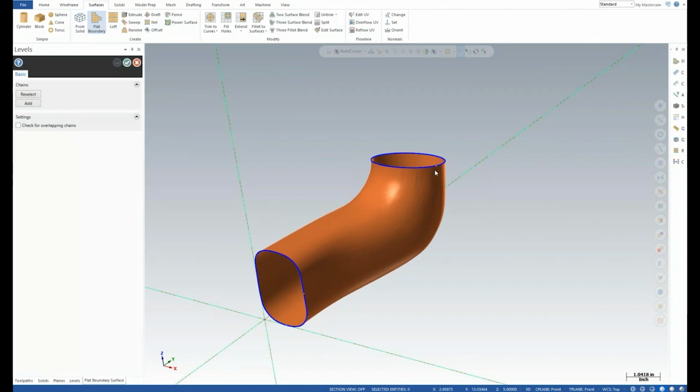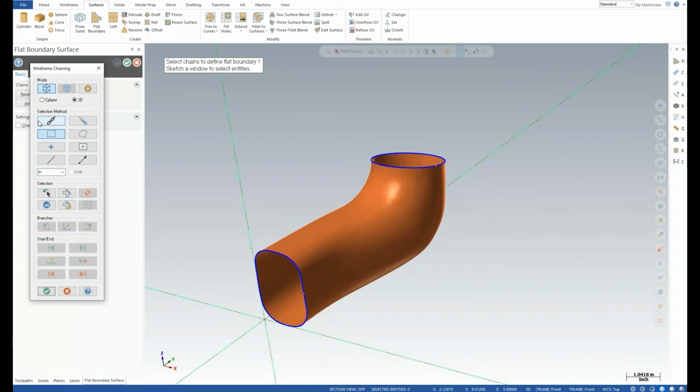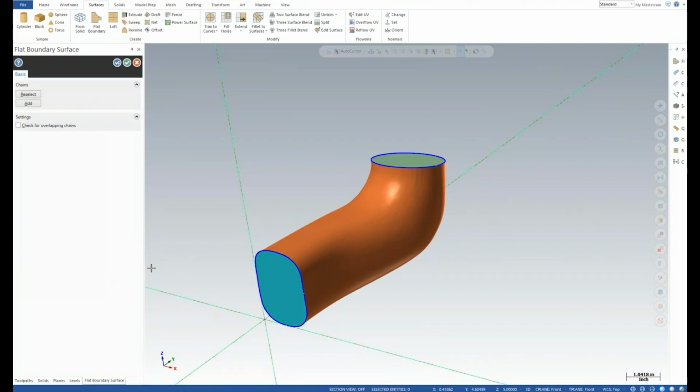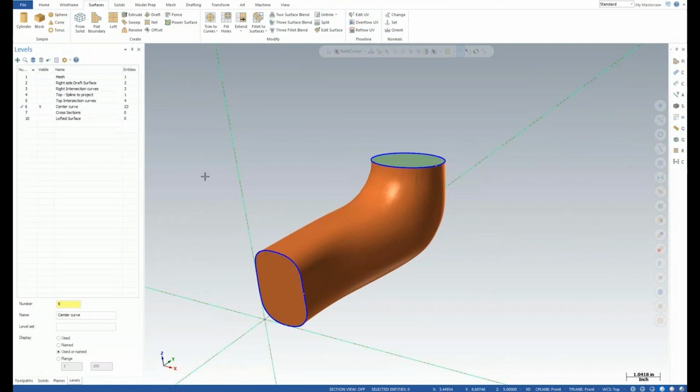Okay, they're asking when creating the curve, does it create arcs or lines when drawing an arc? Basically, when you sliced it, we were just putting splines on there. Yeah, there is an option. It will try to simplify the results, so if it can draw a line, it will. But in this case, spline would be the solution. There is an option on the advanced tab to force everything into a single spline, or you can leave it as individual entities.